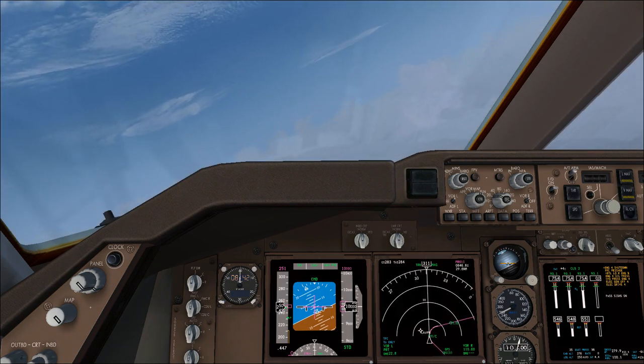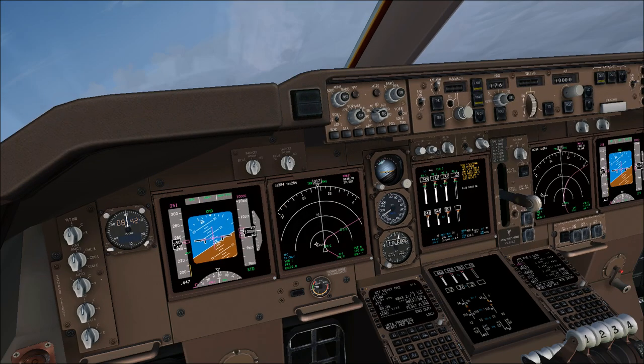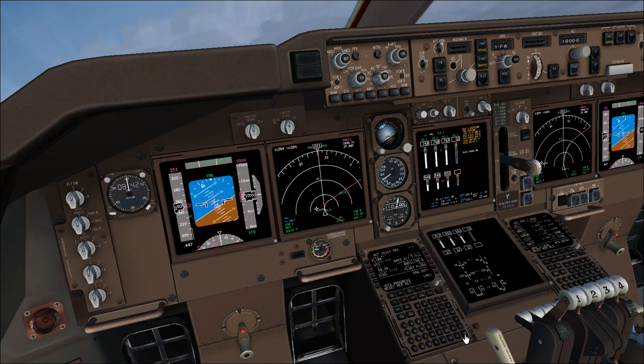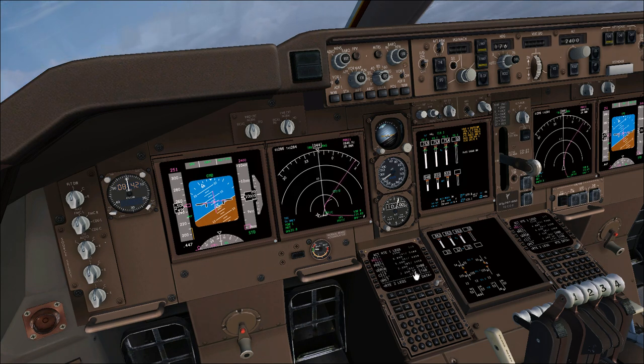We will now continue the flight towards our arrival. We have an FMC message. We set MCP altitude, of course, because we are approaching top of descent. We can select 2400, that is our ILS glide slope capture altitude. And if we go to the next page, you can see we have changed it before.